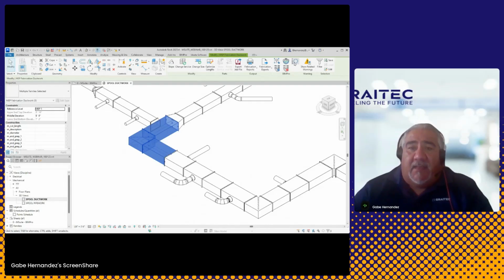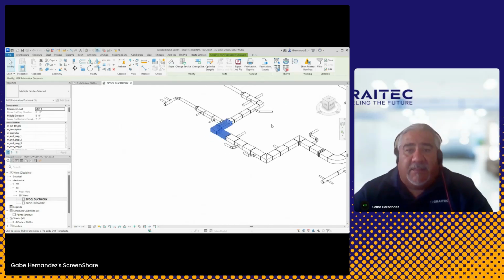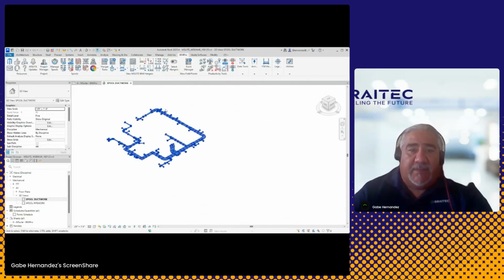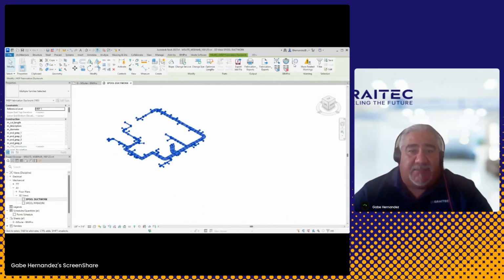And then another opportunity for automation in Revit is the Item Number command here. Natively, out of the box, Revit does not provide number sequencing or numbering of your ITM parts without a third-party application or some type of plugin. So built into this, I can run item numbers if I needed to. If I wanted to, I could have just windowed all this, and then I have that contextual tab to run all these commands.